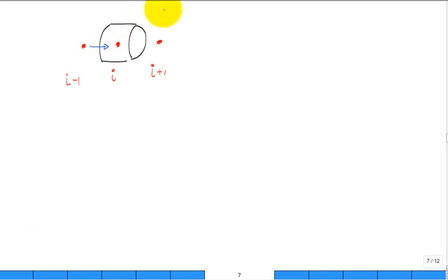Okay, then you have conduction down the axis. You have convection out, and you have, I'll just draw it a little different, heat generation term, GEN. So conduction, convection, and generation. Those are our 4 terms we need in an energy balance for each and every node.